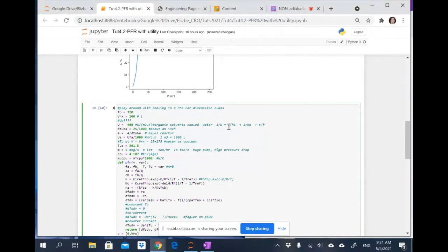So it's the material properties, the thickness of my tubes, and these two parameters, H out and H in, they are functions of Prandtl and Sherwood and all those numbers, which is a function of viscosity and the linear velocity in my fluid, which in turn will be a function of the tube diameter that I choose.